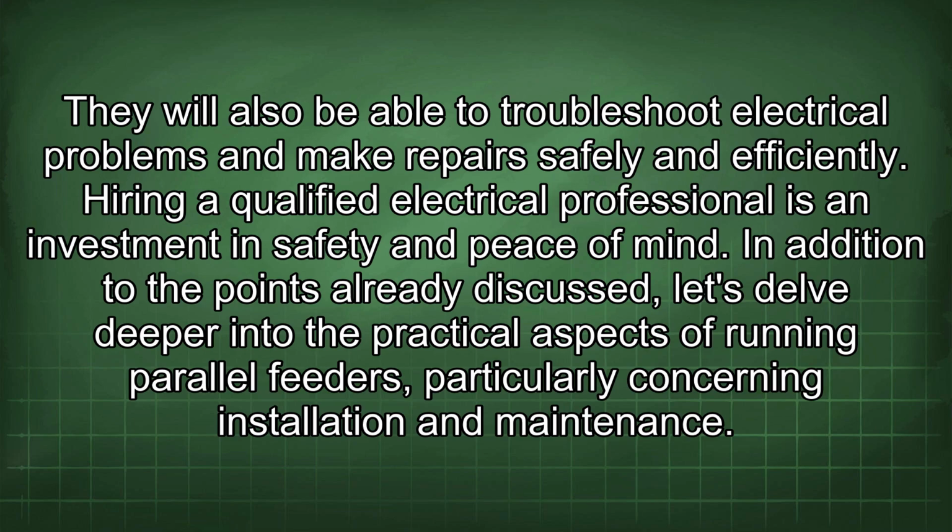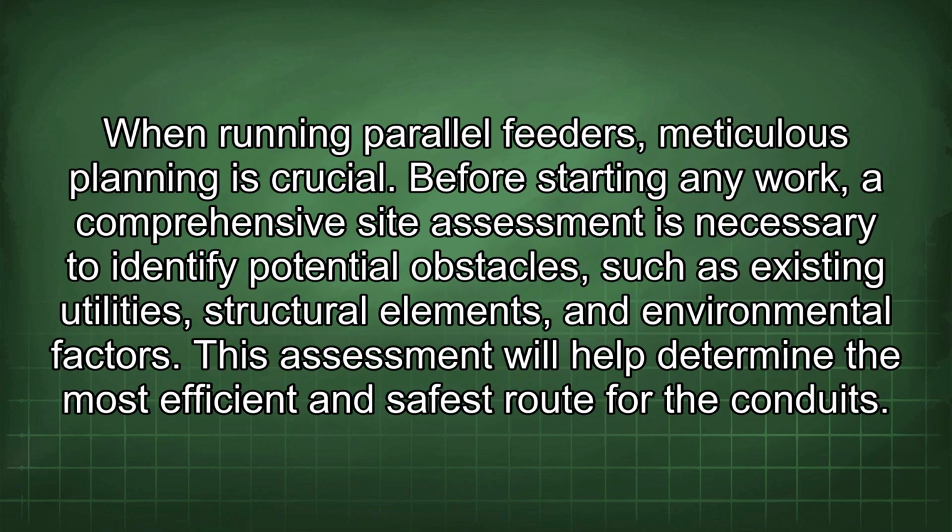In addition to the points already discussed, let's delve deeper into the practical aspects of running parallel feeders, particularly concerning installation and maintenance. When running parallel feeders, meticulous planning is crucial. Before starting any work, a comprehensive site assessment is necessary to identify potential obstacles such as existing utilities, structural elements, and environmental factors. This assessment will help determine the most efficient and safest route for the conduits.